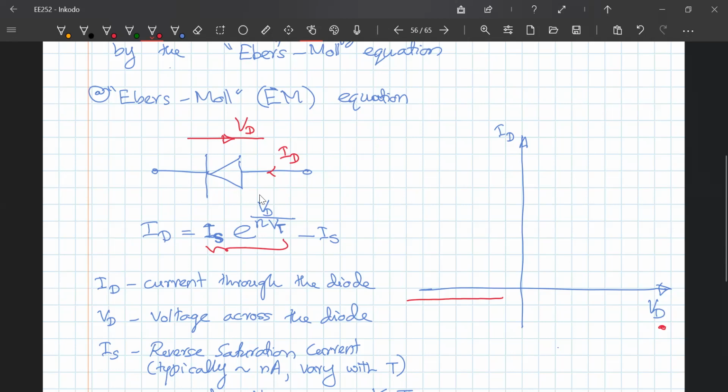It will be just that. Okay, if you plot it, you will see that it looks something like that. This positive part is what you saw as the diode's characteristic. The voltage-current characteristic is basically that, where around here you have what is called the forward voltage.